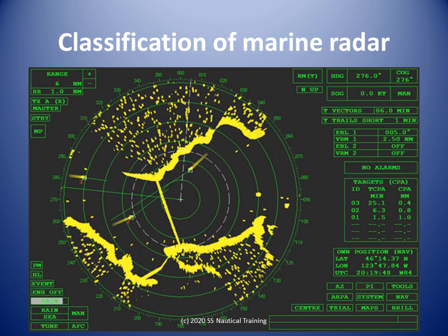It is actually a component of the radar, called the magnetron, that is classified by its transmitting frequency band. There are 2 main frequency bands in commercial radar: X-band, 9000 MHz band, wavelength 3 cm, and S-band, 3000 MHz band, wavelength 10 cm. Magnetron output power ranges from 1 kW for small radars to 60 kW for large radars.